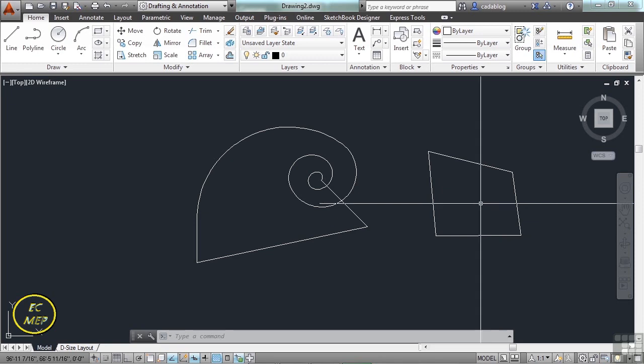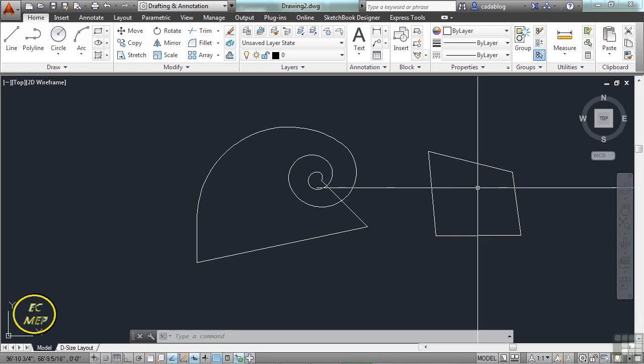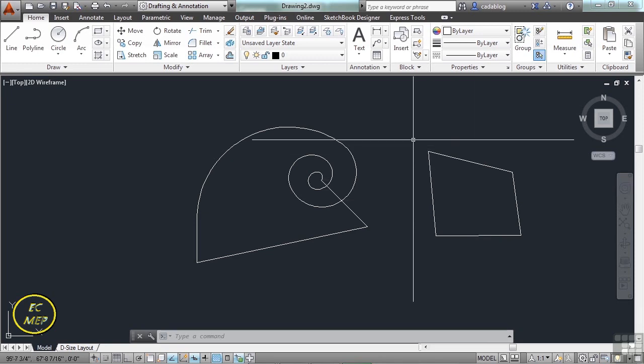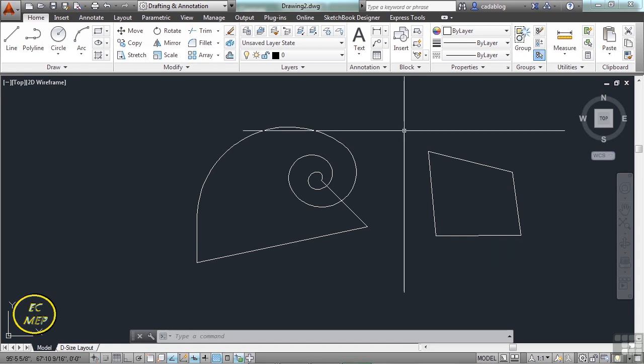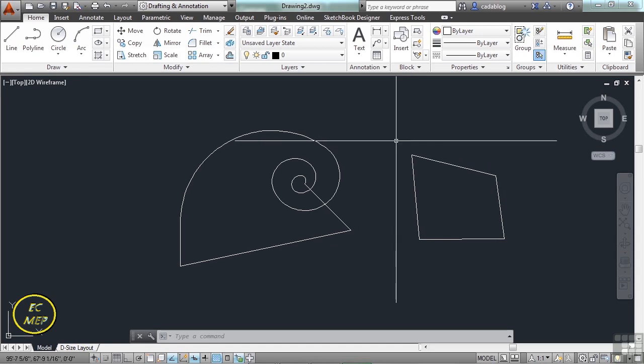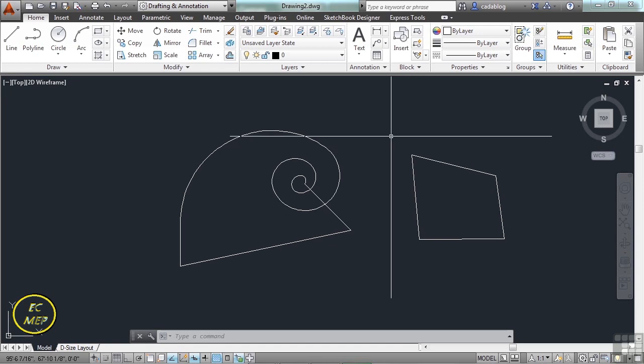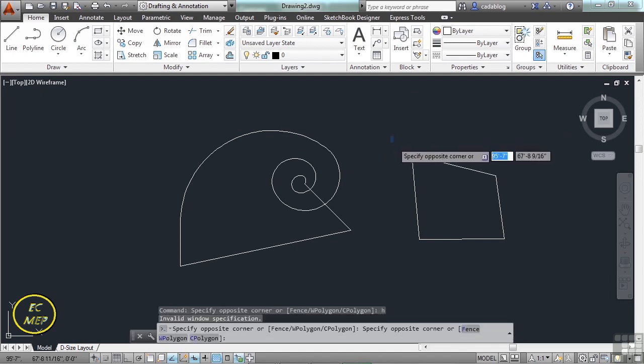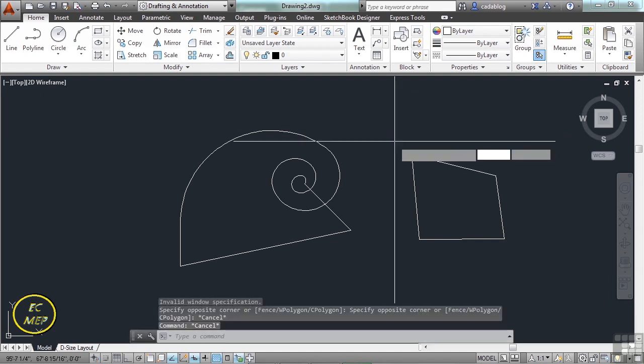Polylines are a bit more versatile. You can do a lot of things with them. We'll look more closely at how to edit them in later sections. But polylines are great, and you're going to use them, and I encourage you to, because you can do other things with them as well. Since they are a closed object, you can very easily create a hatch inside them.